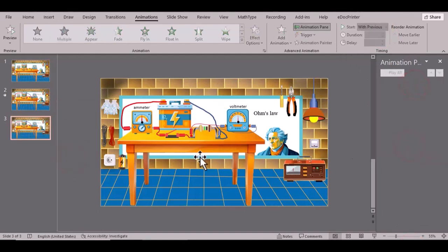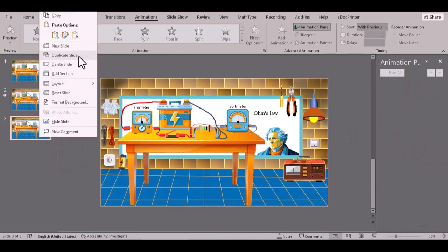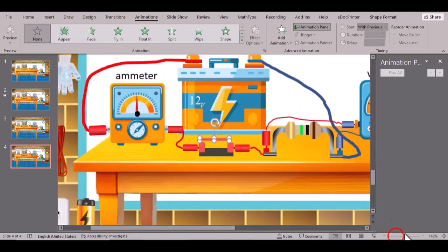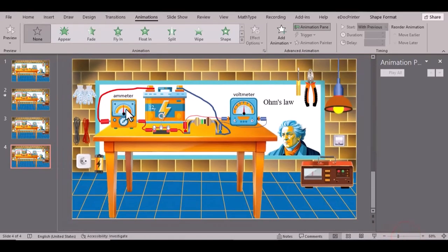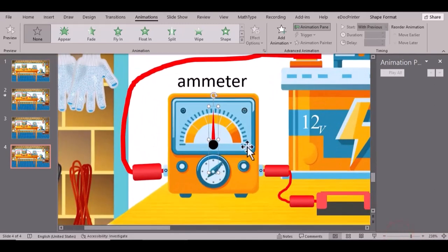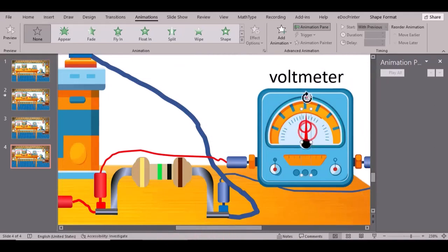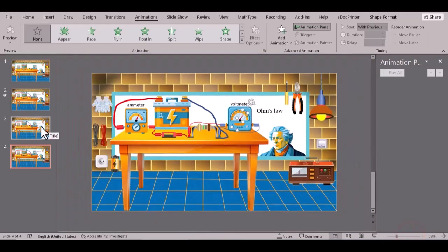Electrical current is the rate of flow of electrical charge past a given point in a circuit, which has the SI unit of the ampere, A, where 1 A equals 1 C/s, 1 coulomb of charge per second. It comes in the form of direct current, DC, and alternating current, AC, and although DC is simpler, AC circuits are used to supply power to most households around the world because it's easier and safer to transmit over long distances.